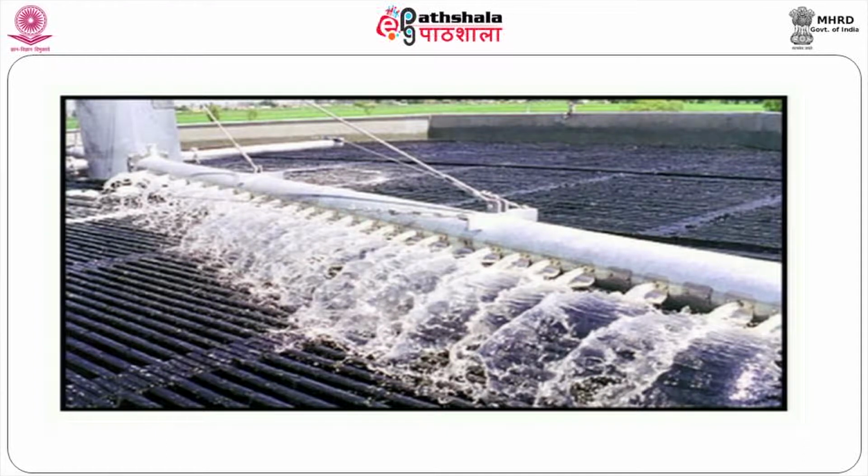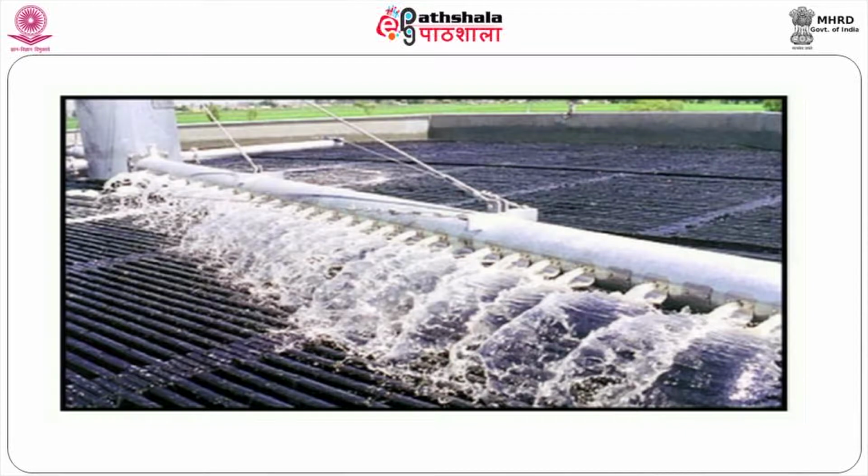With the help of this modular sheet plastic media, we can load up to 1 kg BOD per meter cube per day. With conventional media, we can load up to 420 or even 460 gram BOD per meter cube per day, but the hydraulic loading is less than 4 meter cube per meter square per day. If you incorporate modular sheet plastic as a supporting material for bacterial growth, we can load up to 40 meter cube of water per meter square area per day, so the hydraulic loading is much more. In addition to that, we can load up to 1 kg BOD per meter cube per day. So, the loading rate with respect to hydraulic aspects as well as organic loading is quite high when compared to a low rate trickling filter.